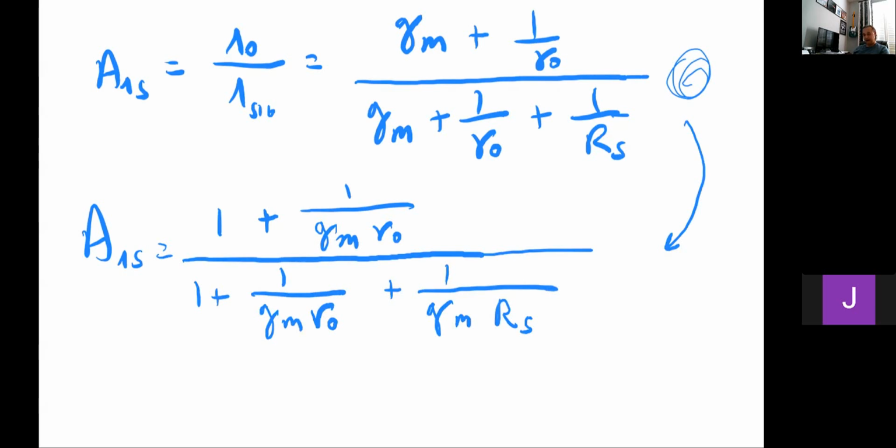It's going to be providing neither voltage nor current gain. It is going to be providing an impedance or a resistance transformation as seen by the common source. So it's going to make the output resistance of the load look larger to the common source original amplifier. Now, because of that, current gain must be about 1. So that's the whole current buffer.